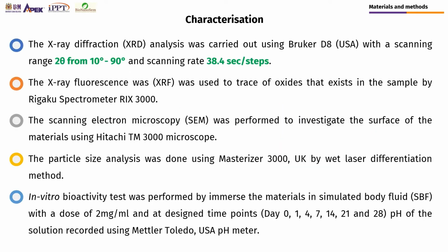For characterization, X-ray diffraction analysis was carried out using a Bruker D8. X-ray fluorescence was used to determine the composition of oxides existing in the materials. Scanning electron microscopy was performed to investigate the surface of the materials before and after immersion in simulated body fluid. Particle size analysis was performed using the wet laser diffraction method.